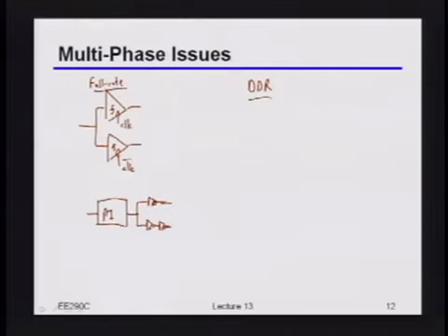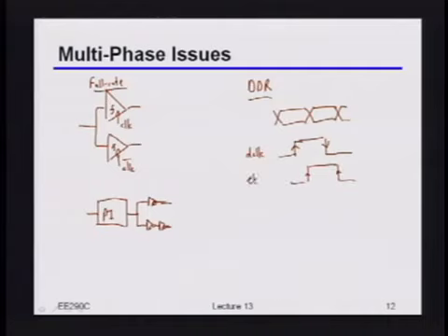So if I look at my clock, I'm going to be capturing data both on the rising edge of the clock and on the falling edge of the clock. So this would be my data clock. Now remember, you still also have to do timing recovery, right? So that means I now need another clock that is 90-degree phase shifted with respect to the first clock. Okay?